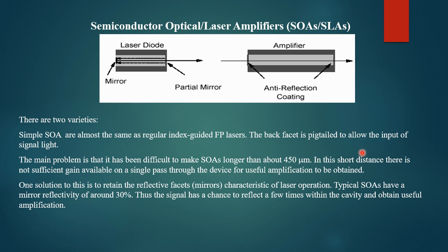Though any direct band gap semiconductors such as II-VI could conceivably be used, such amplifiers are often used in telecommunication systems in the form of fiber-pigtailed components operating at signal wavelengths between 0.85 micrometers and 1.6 micrometers, generating gains up to 30 dB. The semiconductor optical amplifier is of small size and electrically pumped. It can be potentially less expensive than an EDFA and can be integrated with semiconductor lasers, modulators, etc. However, the performance is still not comparable with EDFA.